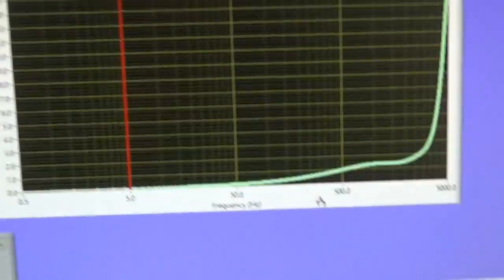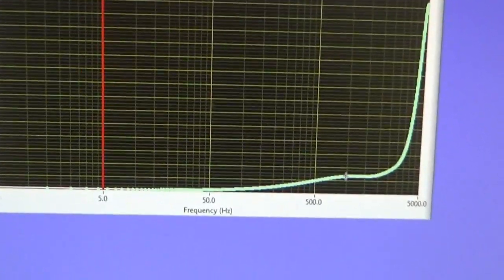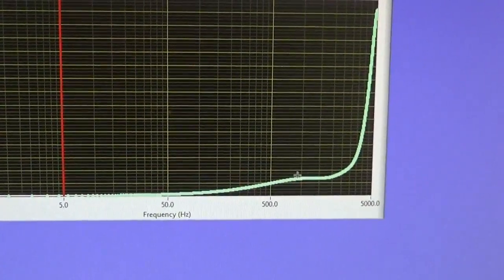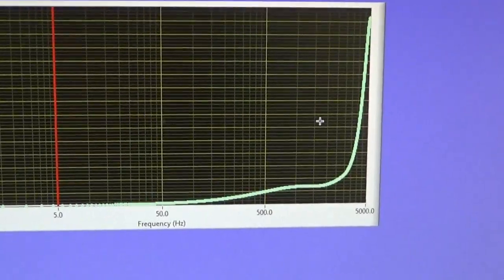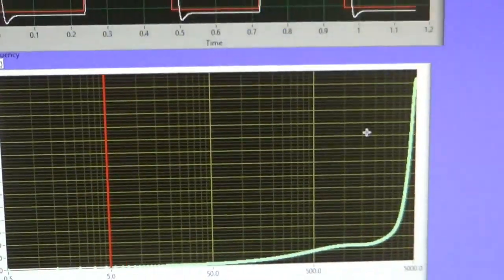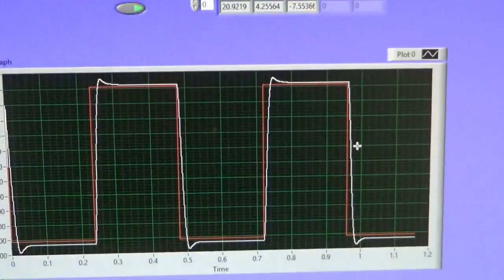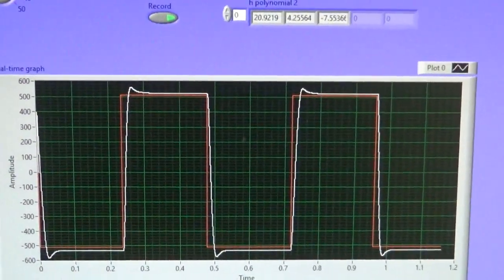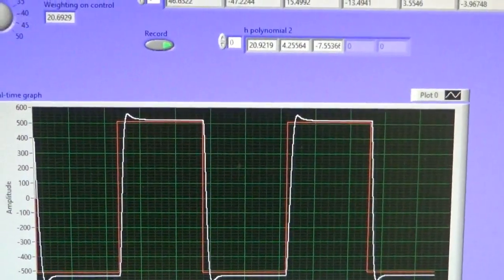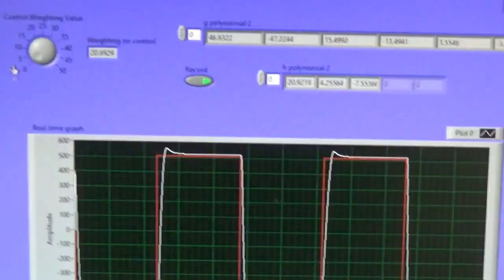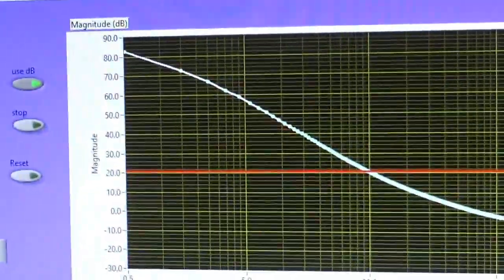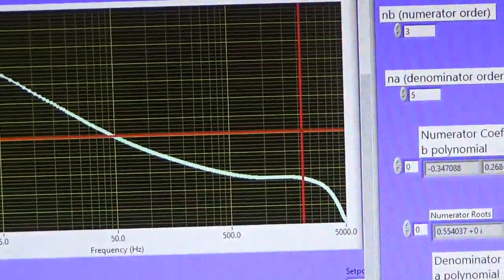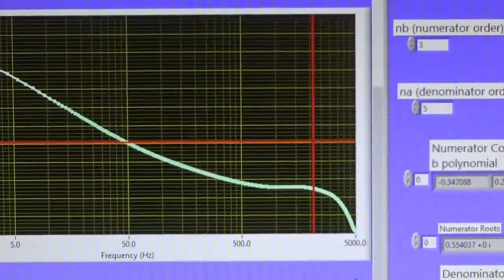And that's the frequency response of the controller, Diophantine, and it just goes up like this at very small slope, and then it seems to shoot up like that. I'm not quite sure. I suppose it's some kind of phase advance, but there it is. It seems to be working. We can run it again. Let's change the weighting. Let's put it down to somewhere low. I didn't of course need to stop it, but I'm just going to run it again. That's the motor turning, doing identification.